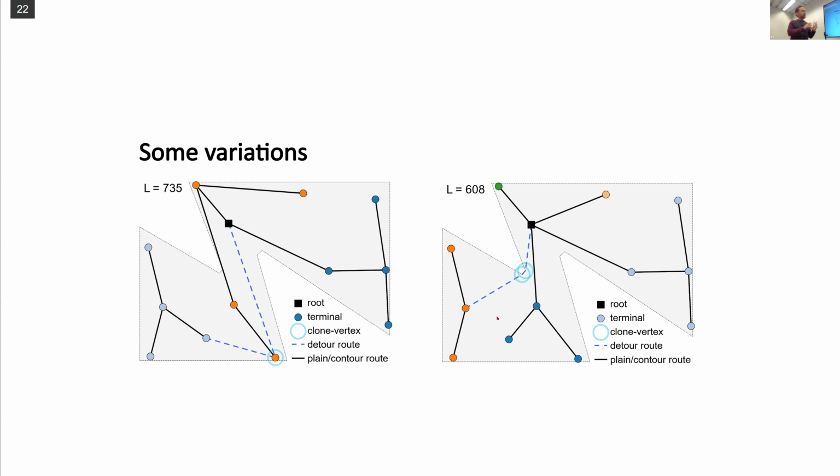So these are the settings that you can tune when you are designing a wind farm collection system. I'm going to use mostly the configuration where you do have a cable capacity limit, but you do allow for more feeders than the minimum possible for that capacity.